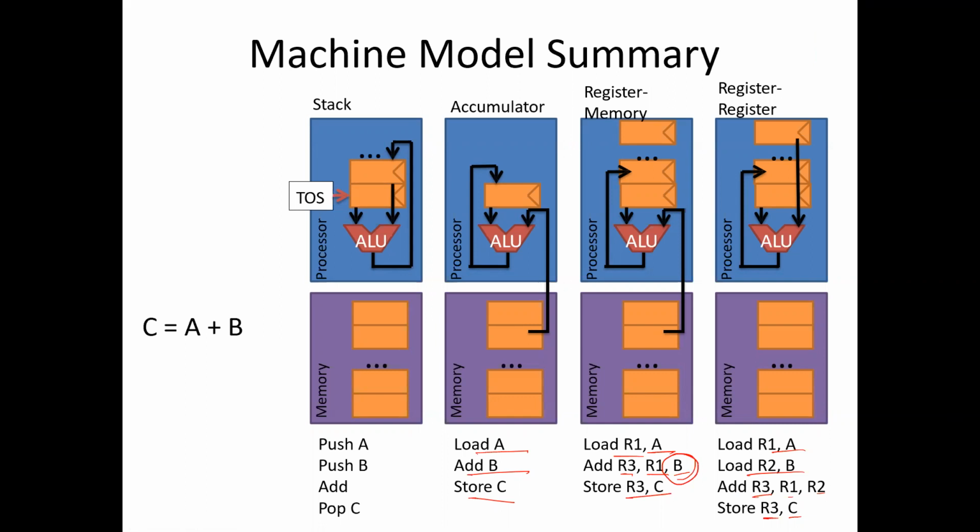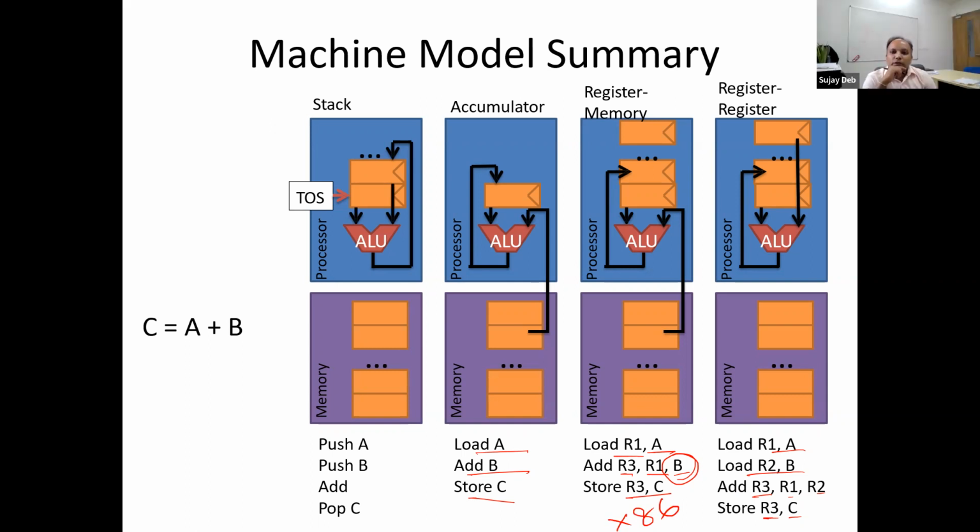So then, can we say that in modern processors being manufactured nowadays, it is kind of a hybrid system in the machine model, implemented between the register model and register memory? No, no, it's not hybrid. They are very clear. So x86 is a register memory model. Most of the RISC processors are register model. At the ISA level, you have to be very clearly defining what your machine model is. It's not hybrid. Okay, sir.